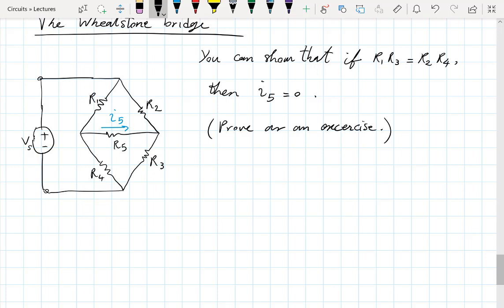Yeah, so if you have a circuit that meets the conditions we've described, which is you have a bunch of independent sources, and you have some dependent sources that have linear relationships, and you have some linear ohmic resistors, and all you want is the Thevenin resistance, well, that's basically just the equivalent resistance of the circuit if you set all sources to 0. Okay?